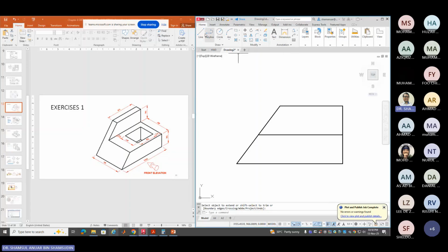So I'm gonna use this thing. I guess I need to turn on intersection. That's good. It's already on. So go here. Don't click anything. Just go to the left. You see that dash lines already appear. You type 12. Then go down until you get that X. So that is the intersection. And this thing is 42 in that direction. So I'm gonna just copy that.